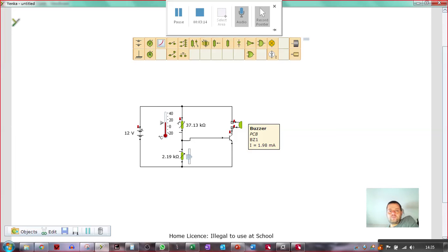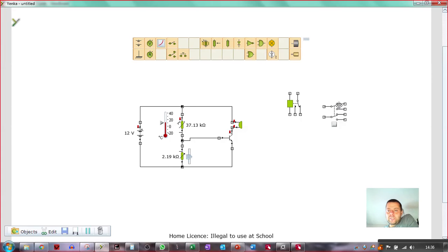How do we do that? That's where a relay comes in. So a relay is a component. Here's the relay here. There's the symbol for a relay. And you can see that half of the symbol is just a switch. You actually get different relays with different switches in them. Relays are named for the kind of switch that they've got. So that's a single pole double throw relay. And you can get single pole, single throw, and so on and so forth. You know all the different switches by this point, hopefully.